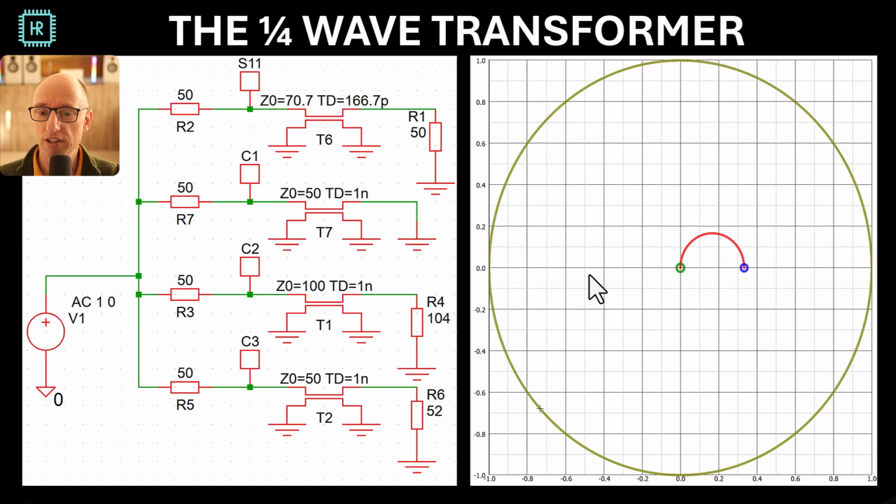I can draw a nice Smith chart. I cannot draw all those nice wiggly lines that I did in Python, so I have to construct something to make it look a little bit like a Smith chart. Now C1, what I've done here, I've picked a short and then a 50 ohm transmission line. So what does that mean? The short is here on the left, the 50 ohm transmission line in the middle. So because of this theory, the impedance starts rotating around that center point, and that makes the outer circle of the Smith chart.